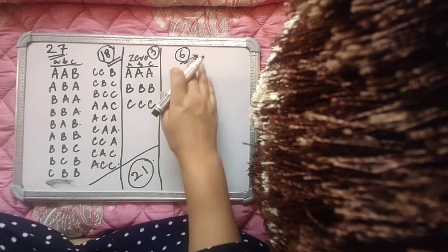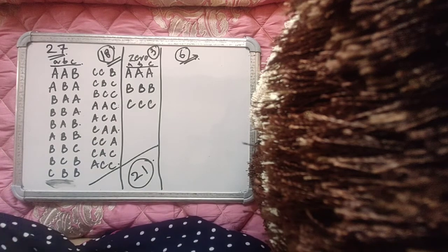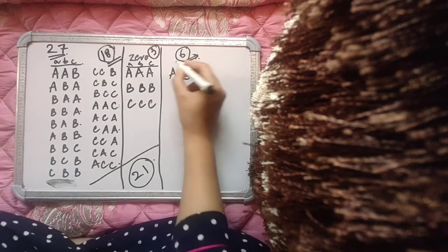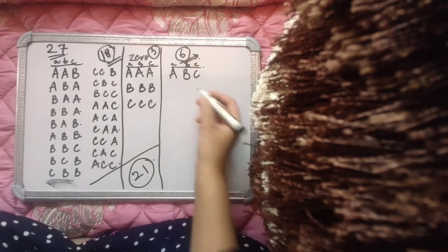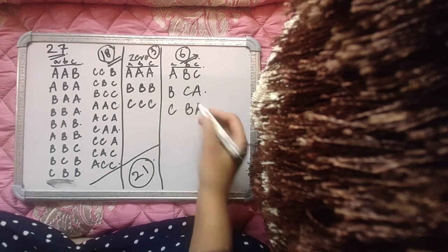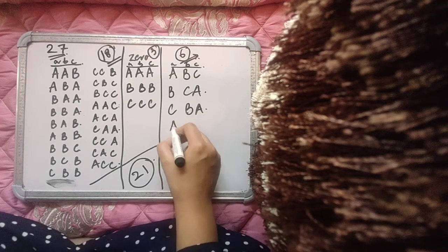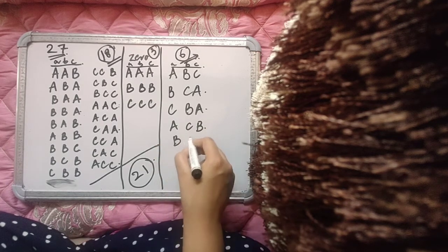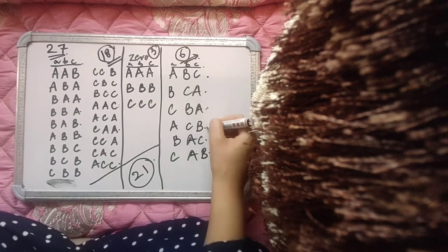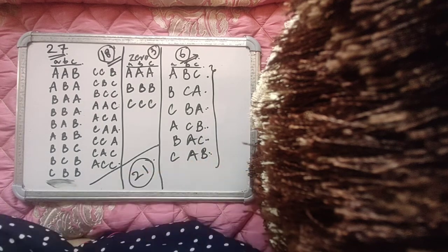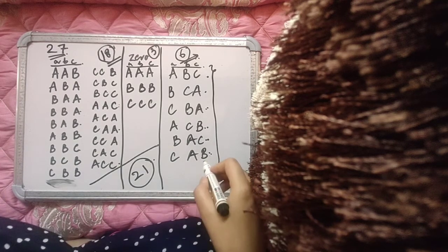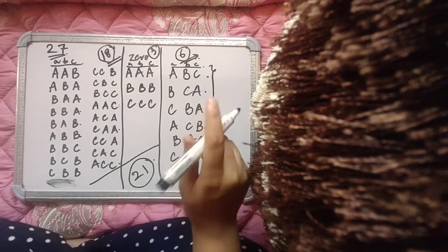These 6 states are those states that switch a unique input phase at each output, which means something like A, B, C at output phases A, B, C, or B, C, A, or C, B, A, or A, C, B, or B, A, C, or C, A, B. So these 6 states, 1, 2, 3, 4, 5, 6, are also switched sometimes, but most of the time they are discarded because they result in a rotating space vector, which I will discuss with you.